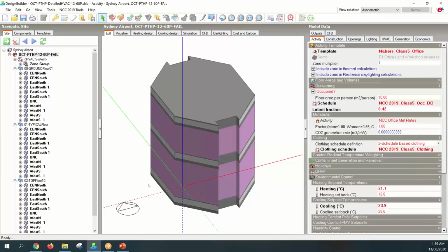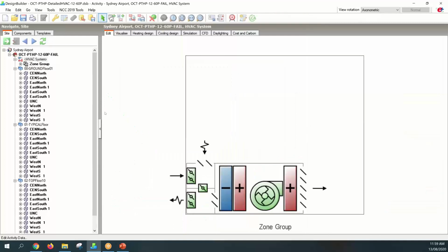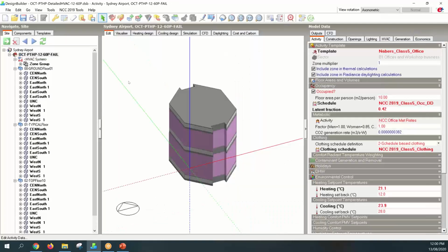Now, I have used a real air conditioning system, a DTS compliant air conditioning system as required by JV3. I haven't put a complicated one because that's a completely different ball game, but just as a DTS system, I've got a reverse cycle heat pump, which takes outside air. There's a cooling and heating reverse cycle coils. There's an electric defrost coil, and there's one in each of these zones. And that's sufficient for what I want to do, which is really look at the fabric.